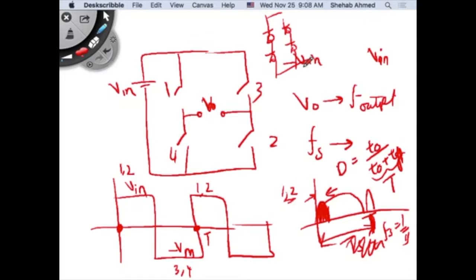But yeah, you can take this inverter and supply an AC load, and no problem, it will work. And the benefit here is I'm switching at a very low frequency, so my turn on and turn off switching losses are very low, and I'm supplying an AC waveform. It's great, but I have a lot of harmonic content.